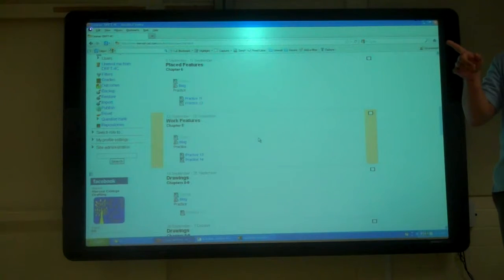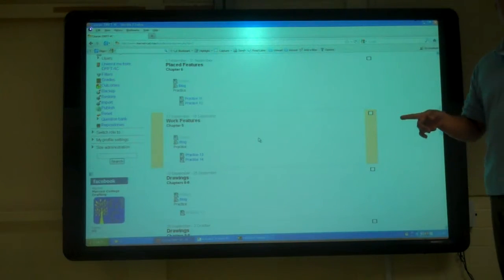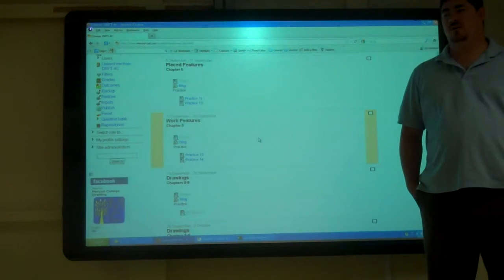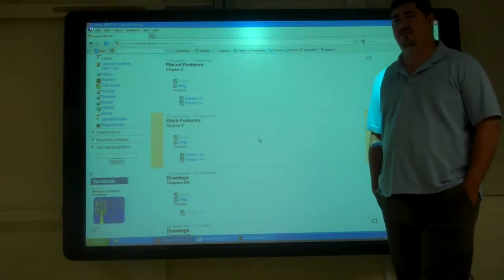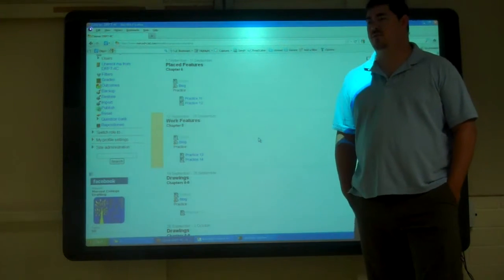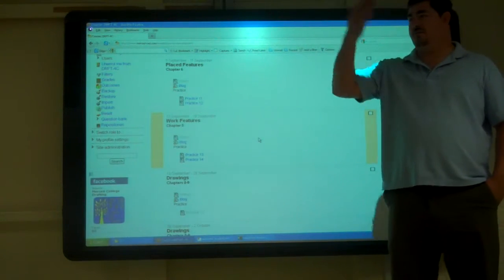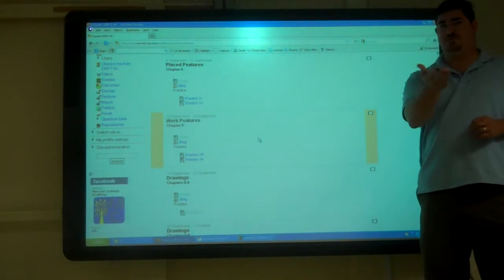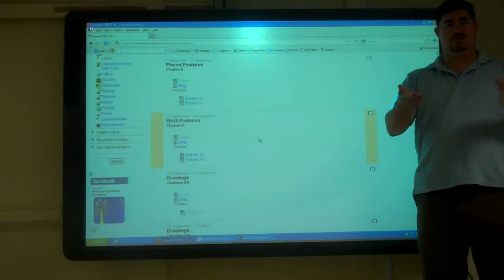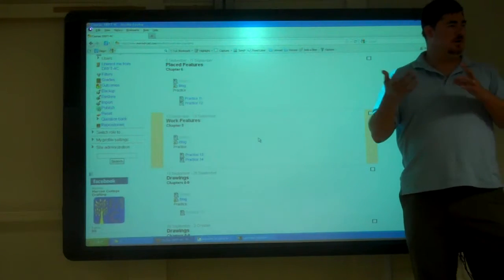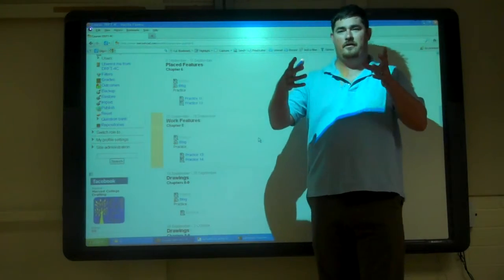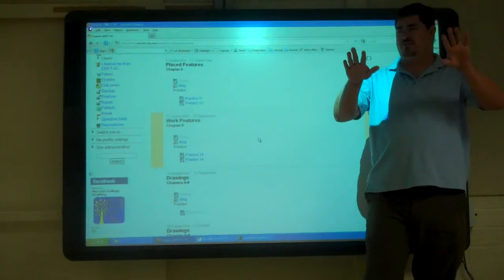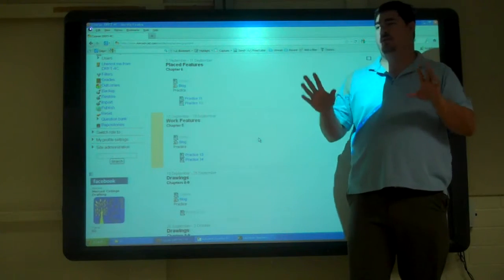Kind of. So what do we need to be able to sketch? You need to sketch. What do we need to have in order to sketch something? Lines. A working plane. We have to have a plane, right? Yeah. Or something flat to draw on. So sometimes, like so far we've had the base planes, the XY, the XZ, and the YZ, right? The base planes. And once you start a part, then you have the flat faces on the part that you can draw from.